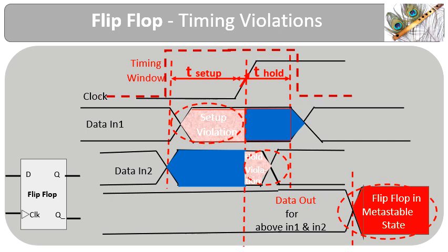In synchronous digital design, flip-flops rely on precise timing between data and clock signals. The timing window defines the safe interval around the clock edge, where data must remain stable. This window spans from T setup before the clock edge to T hold after it.